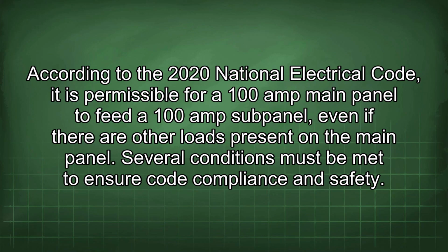According to the 2020 National Electrical Code, it is permissible for a 100 amp main panel to feed a 100 amp subpanel, even if there are other loads present on the main panel. Several conditions must be met to ensure code compliance and safety.